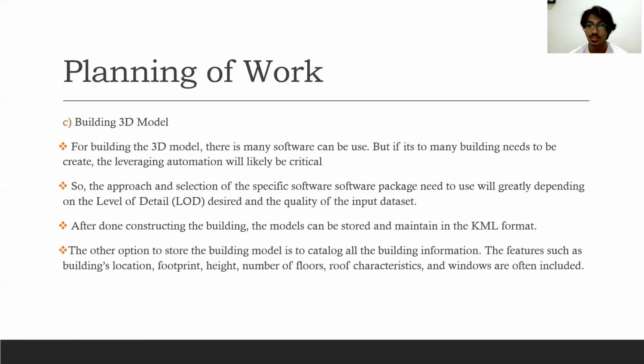The specific software package to use will greatly depend on the level of detail, or LOD, desired, and the quality of the input data set. After constructing the building, the models can be stored and maintained in the KML format. As another option to store the building model, a catalog can also be used. Features such as the building's location, footprint, height, number of floors, roof characteristics, and the windows will often be included and maintained in the catalog.